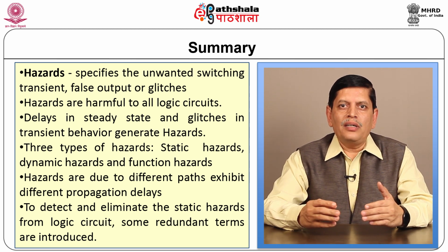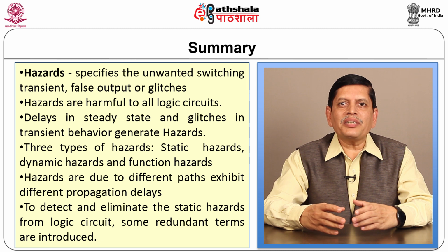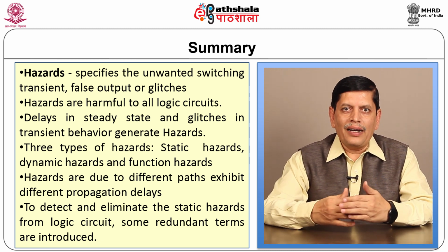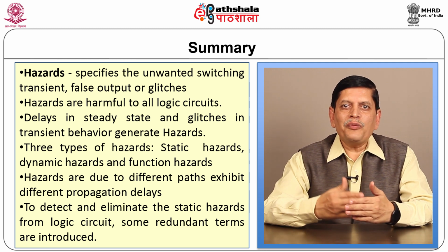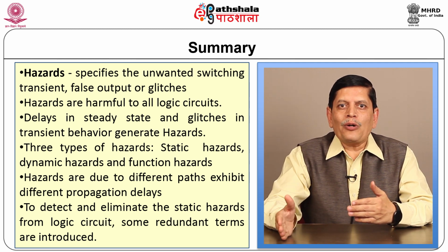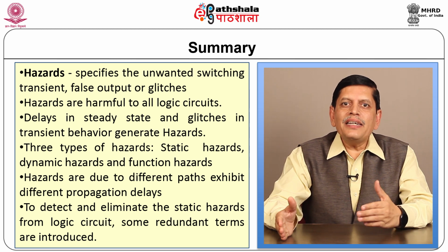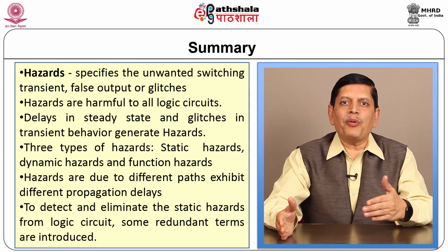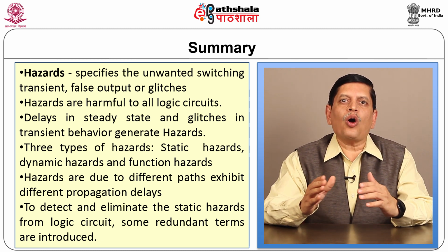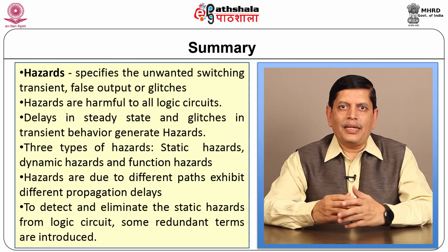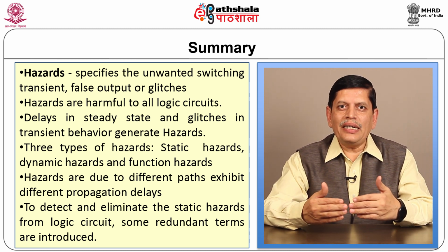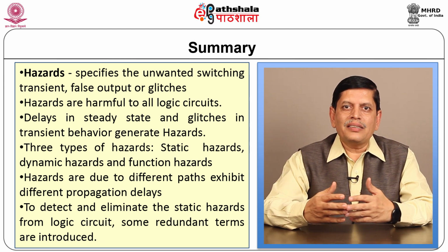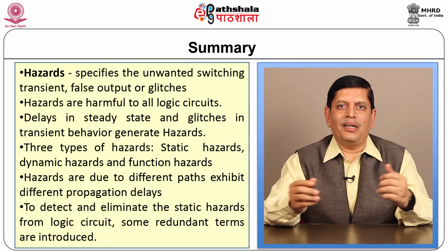When we talk about any combinational circuit, these are no longer ideal combinational circuits. If there are signals appearing through different gates at the input of the combinational circuit, definitely there is a possibility of certain delay, and this delay is the propagation delay present in almost all combinational circuits. Now, whenever we are designing the combinational circuit, we need to look at the realistic picture, wherein there are 3 different types of hazards that are possible.